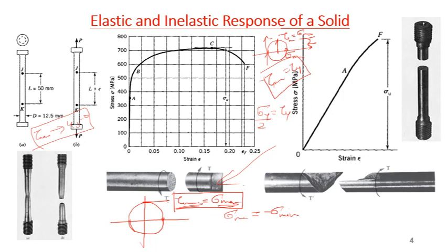But if you have a biaxial or triaxial state of stress, when we have a 2D or 3D stress state, it becomes difficult. For example, this is for the brittle material and it fails under sigma max, but in that case, that is equal to the maximum shear stress as well. So how do we link this material property of yield strength with multi-axial loading? We will discuss it briefly in this course, but in detail in the next course, Mechanics of Solids 2. But just to give you an idea why we are calculating the stresses, principal stresses and maximum shear stress.